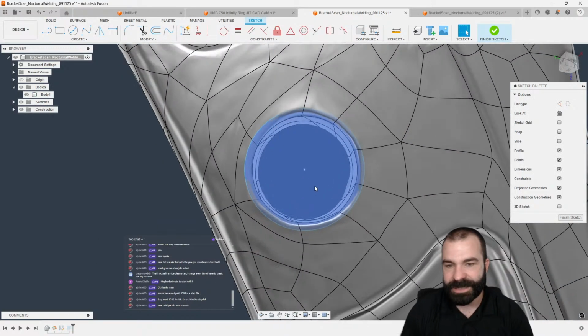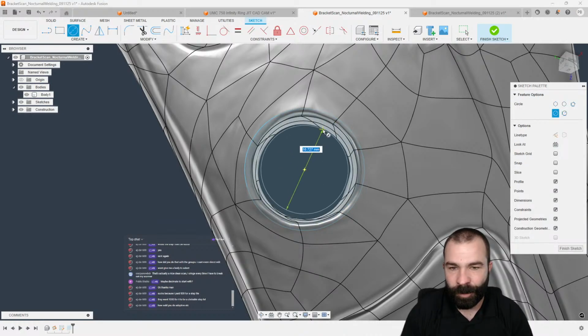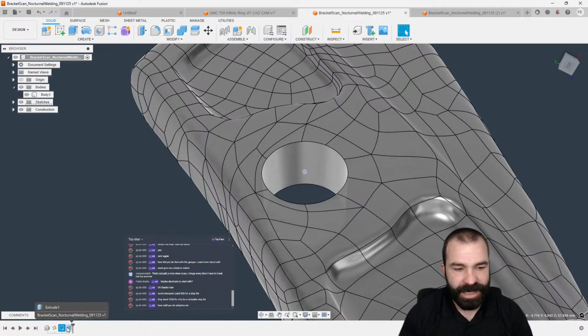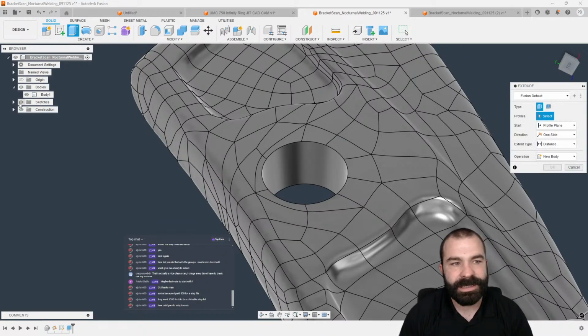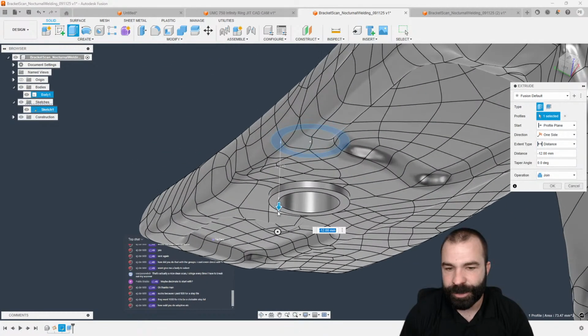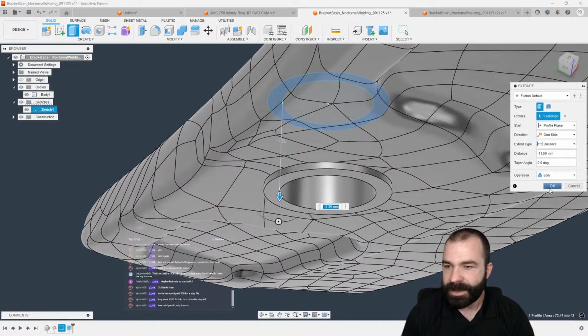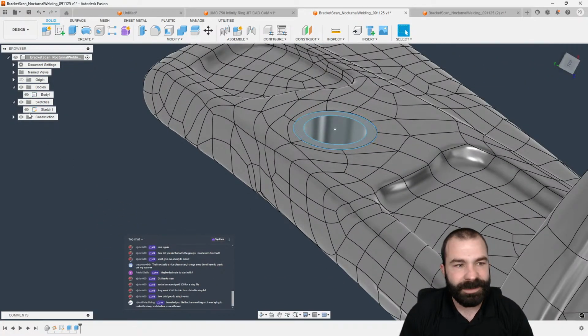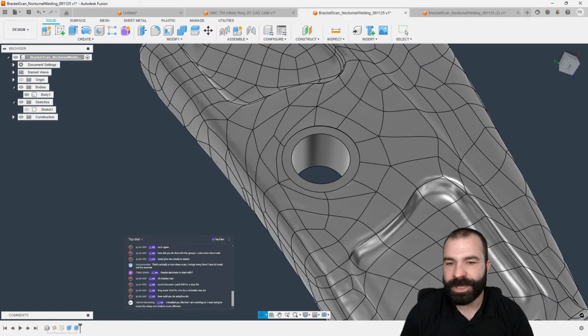Again, just so you guys know, if you're paying attention at home, here's like a 2-cylinder move. Let's say, for example, initially I cut that out. Then I do a secondary extrude, turn that sketch back on, grab that outer profile. And just like that, I could recreate whatever is there, right? So again, it's a down and dirty way to do it. As you can see, that would give me that whole location, a machinable hole nonetheless.